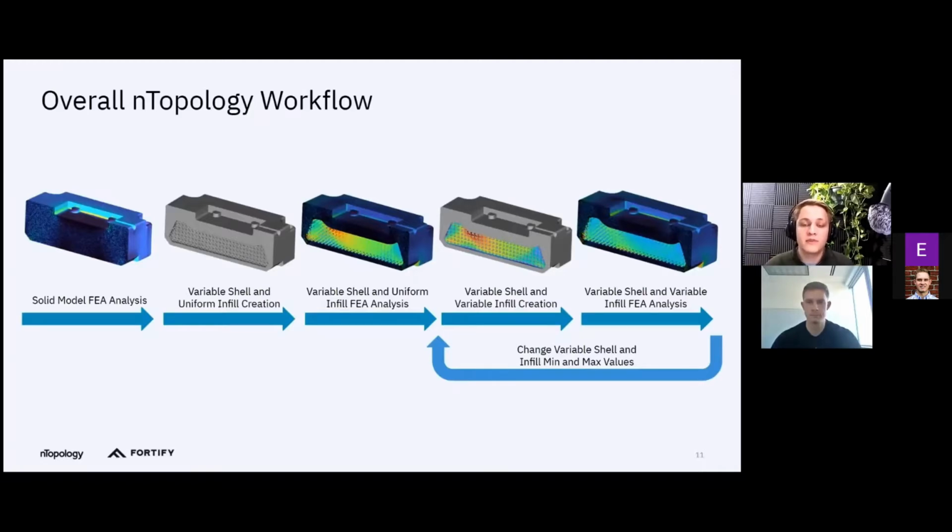If I say, okay, my beams are too thin or too thick, I have too high of stress or displacement, whatever it is, I just get to change those values, right? And nTopology's reusable workflows allow it to just rerun and tell me if I'm right. So I can say, okay, this isn't thick enough, let me change it. Instead of 0.5, I'm going to go 0.6 or 0.7 or 0.8. And nTop just reruns and reruns until I hit my design goals, right? That's a really fantastic part of those reusable workflows that we've been talking about.